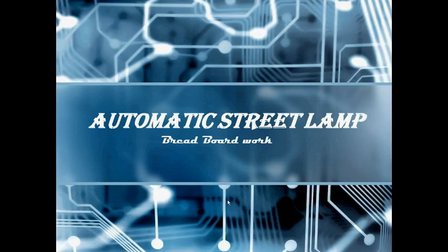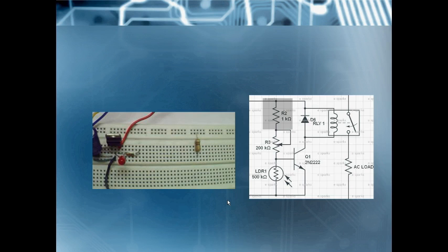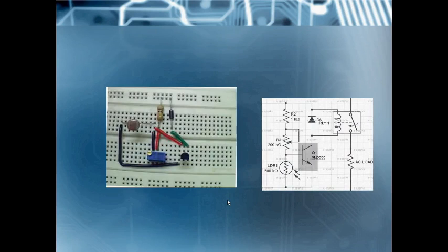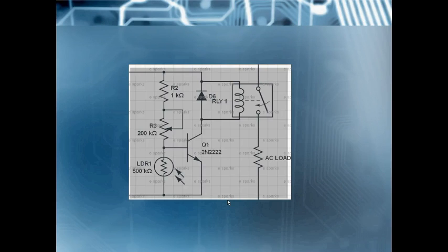Let's have a look at the breadboard work now. I connected the entire power supply circuit at once. Next step is to connect the resistor and a potentiometer in series with the resistor, and the LDR in series with the potentiometer, one of its ends going to the ground. And the second part of the circuit: the diode and the transistor whose emitter is grounded, base is given to the LDR potentiometer junction, and the collector to the diode, and finally connect the relay across the diode ends.